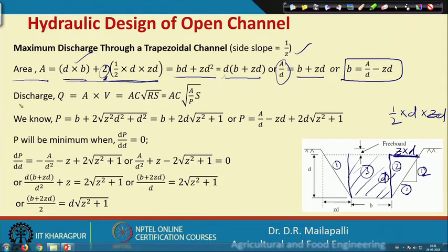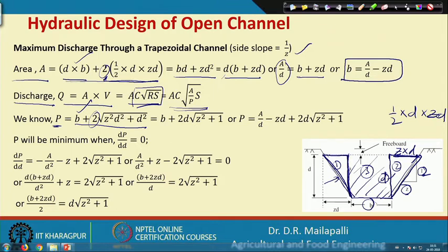Then the discharge, the same step, Q is equal to A into V. You change this velocity equation and you end up with this term. And P is the wetted perimeter. For the wetted perimeter, this length plus this length plus this length. This length is given as B, and these two are equal, so once you know the length of one of them, you can multiply with 2. The length of this will be, this is the triangle.